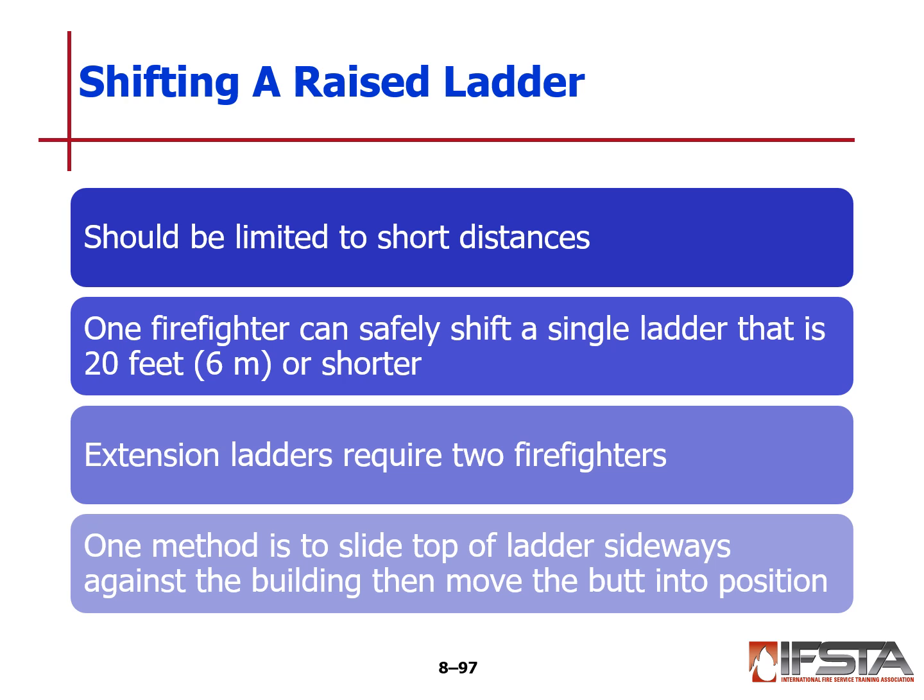If you look up and see that you're not going to catch on anything, you can begin to flip this ladder over and over from the side, and you can move it pretty easily by yourself. One method is also to slide the top of the ladder sideways against the building and then move the butt into position. Some of this may depend on the type of terrain that you have on the ground and the topography.